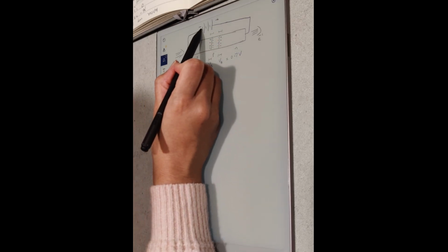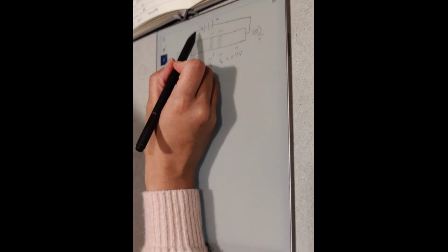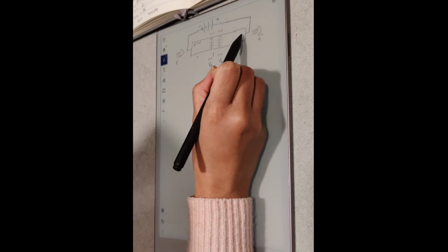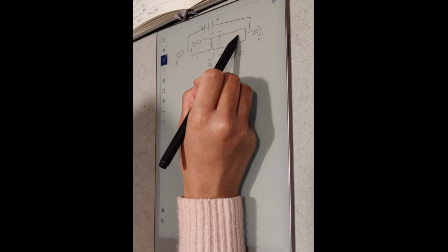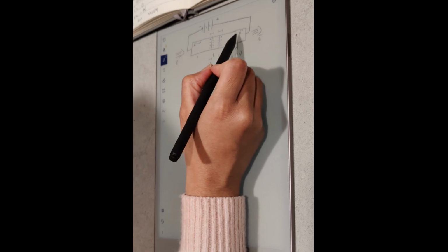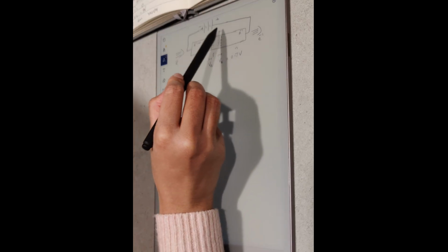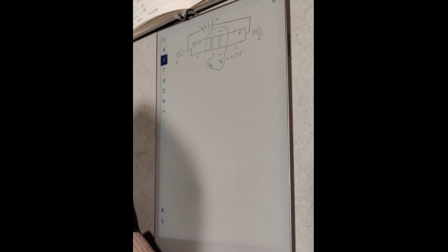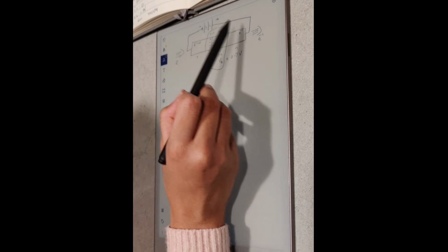Why? Because of this negative terminal, the electrons here are going to be repelled. So electrons are going to start moving in this direction. Now what's happening here? So this is a positive charge. Therefore, the electrons that are here are going to get attracted. So electrons are going in this direction. So that's good. We have electrons going this way, and we have electrons going this way. However, we have a potential barrier that we are unable to cross at this point. So therefore, there is no current that is flowing through this whole circuit.